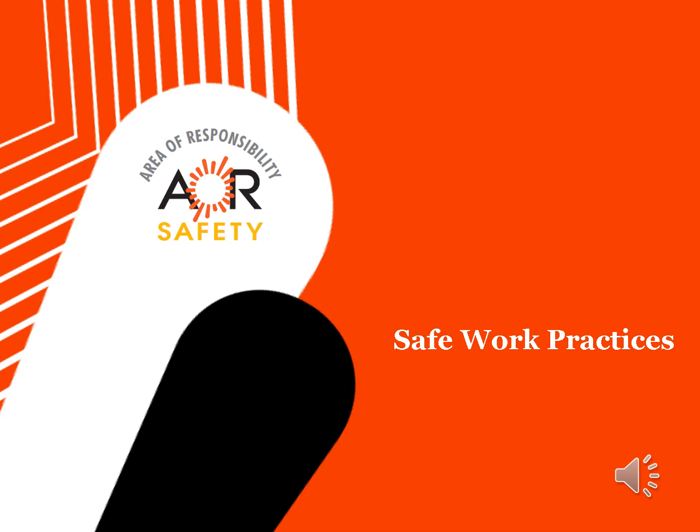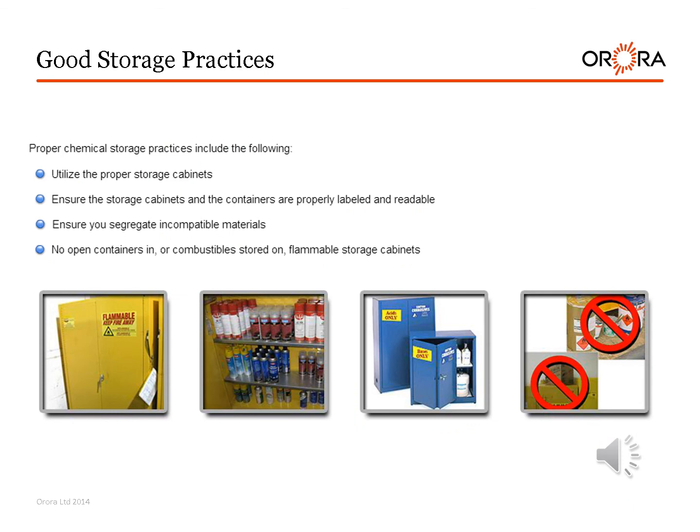Safe work practices. Good storage practices. Proper chemical storage practices include: utilize proper storage cabinets. Ensure the storage cabinets and the containers are properly labeled and readable. Ensure you segregate incompatible materials. No open containers in, or combustible stored on, flammable storage cabinets.